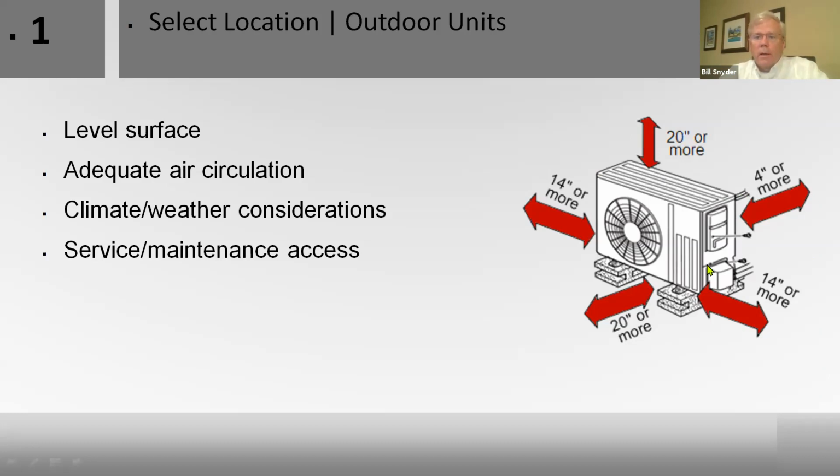This side and the top is where the controls are. The control is sitting right in here and on this side. So it says 14 inches or more. 14 inches, can you squeeze in there as a service guy and actually work in a 14-inch space? I'm not that big. I don't think 14 inches is enough. So just consider leaving enough space.